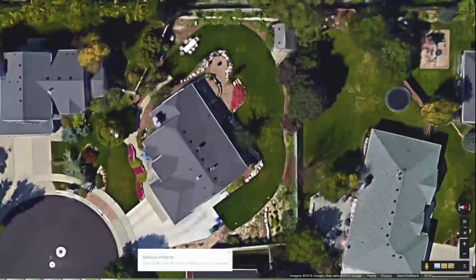So, okay, measuring distance. So we basically came out to, okay, from here. Now if you drag it, you can change where it goes. Separately click that. Get that to the property line. All right, so we're about 3 feet. And then we bring this down here to this edge because this is a known edge. And now we're at 30.89, so roughly 31 feet. So that gives you a fairly good idea of how that tree sits in relation to everything else. And you would do that same thing to site existing trees.